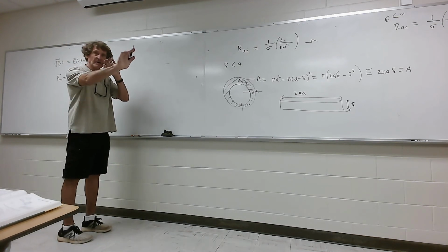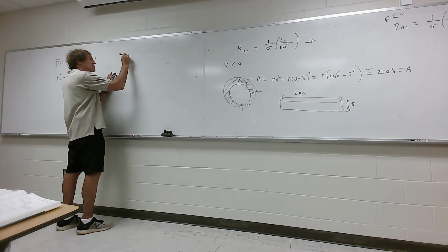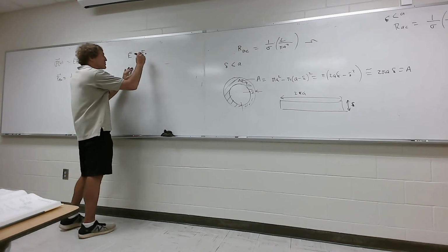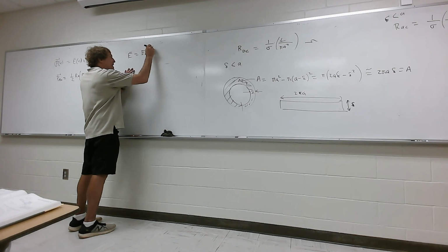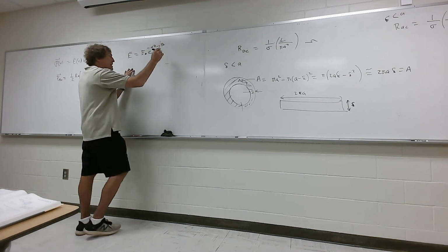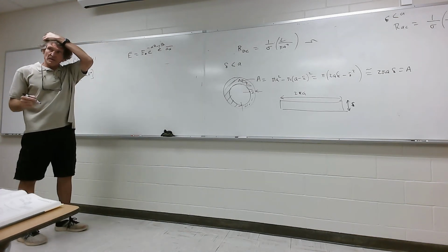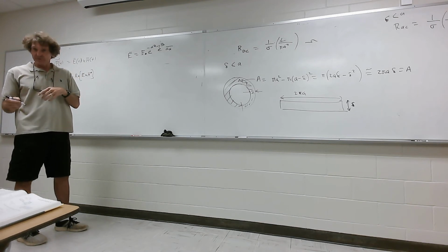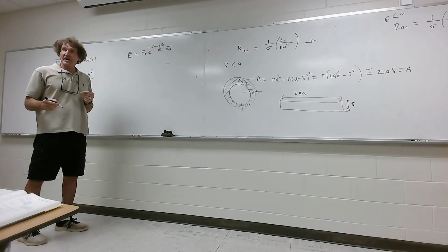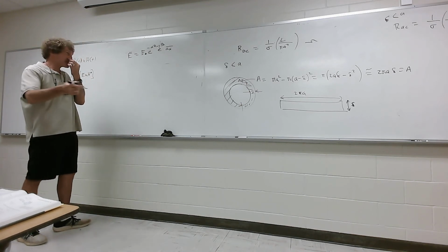We're assuming it's propagating in the Z direction, and it has an X orientation for the E field. So if my E field in general is given as some E naught times e to the minus alpha z times e to the minus j beta z, and it's in the AX direction, then the actual H field that would come from this, right? We can go ahead and take 1 over eta times the unit vector in the direction of propagation crossed into the E field. But we've done this several times already.